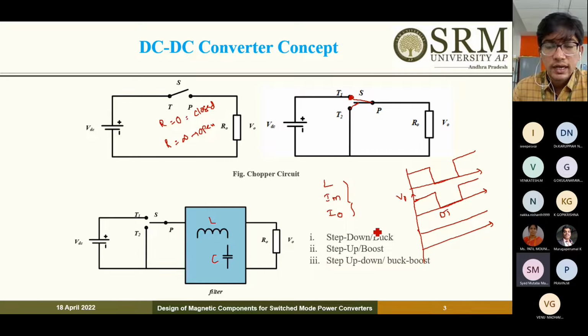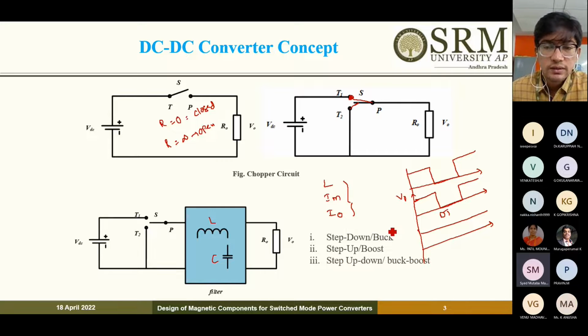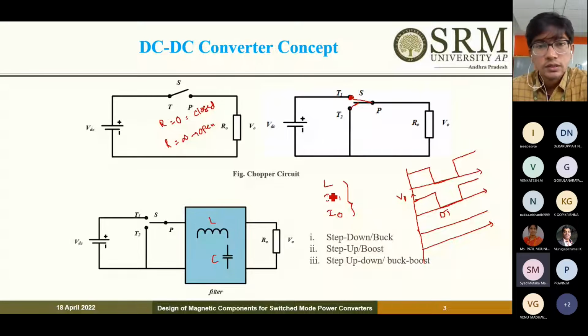These are the parameters we need to obtain by designing any conventional converter or advanced converter. Here first I will take up an example of a conventional buck converter and explain the design procedure. From that design, we'll start understanding how to design an inductor, how to find the number of turns, what kind of cores we need to use, and which gauge of wire we need to use.